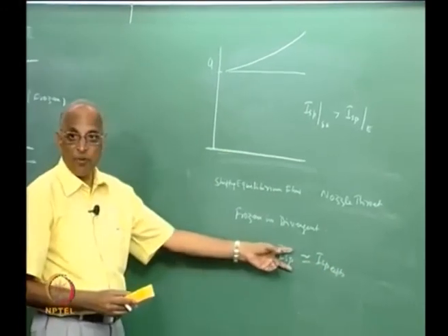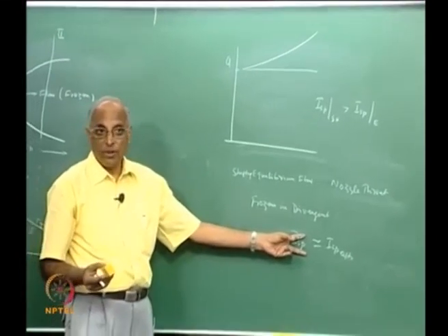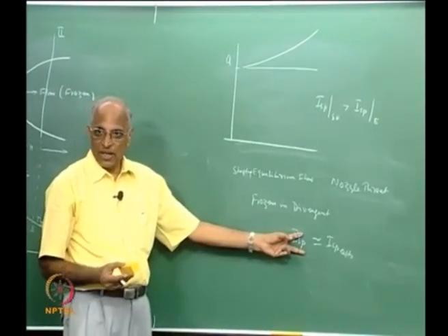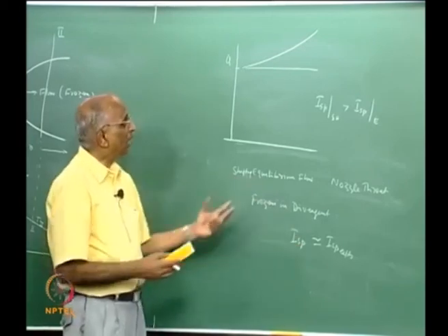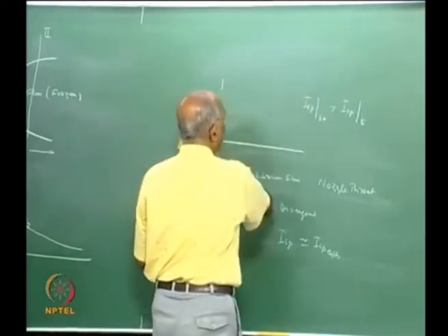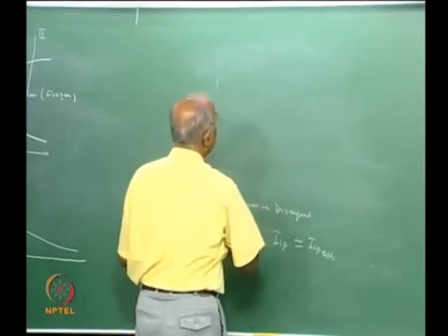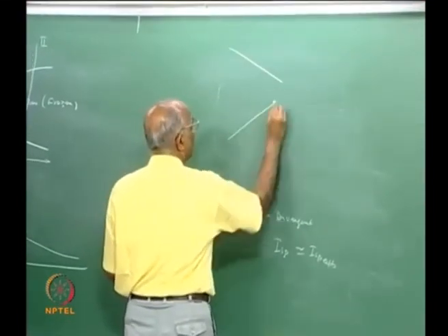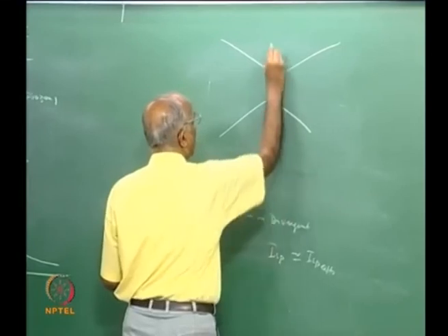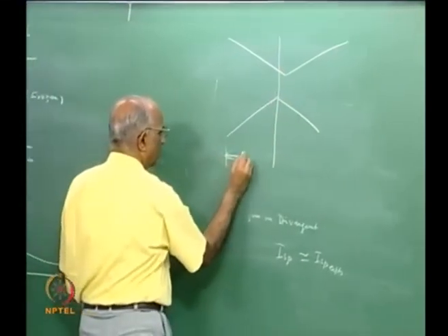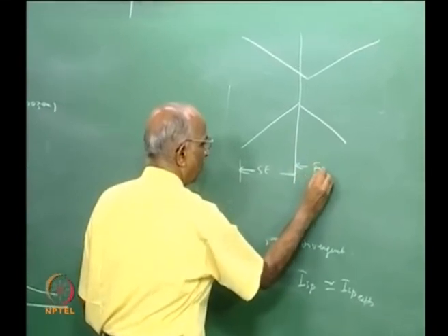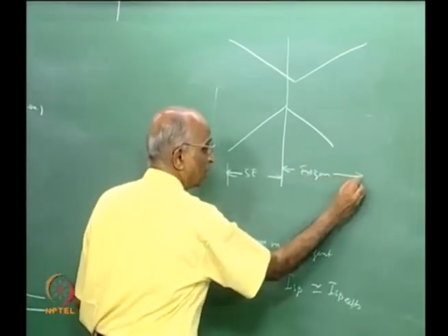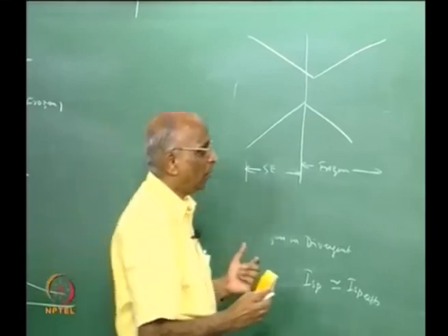It depends on the type of gas, the type of dissociation, but for hydrogen oxygen there has been published work, the Bray model and all that, which assumes, let us just put it down, supposing I have a nozzle, convergent followed by divergent, I have in the convergent shifting equilibrium flow and in the divergent frozen flow, which tends to give me a reasonable value. If not, what is going to happen?